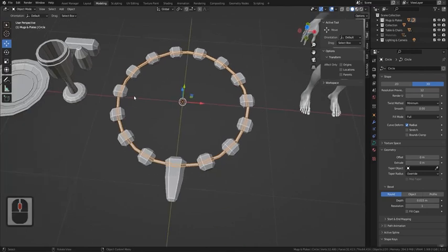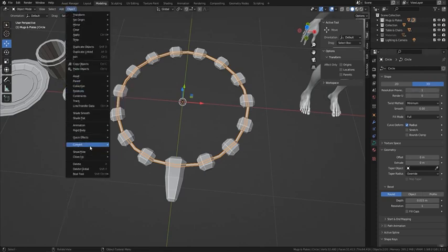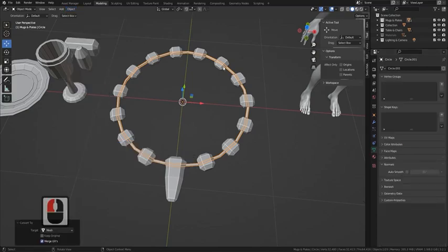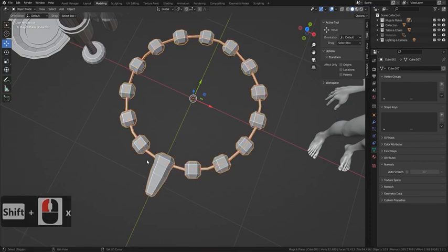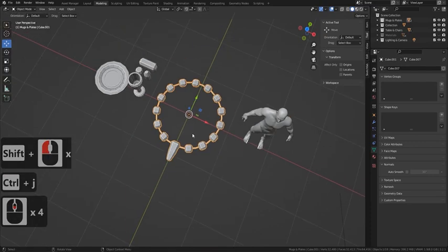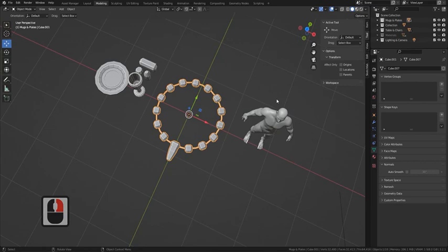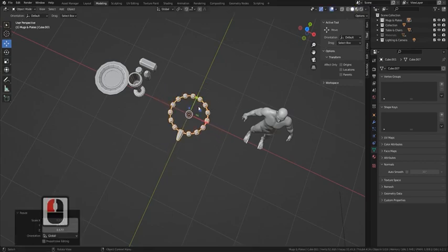Now, when you bring in a piece of mesh like this, normally I can't turn down the resolution because you've already created it. So this actually has no effect. Finally, all we need to do is come to Object, Convert, and convert it back to an actual mesh. And there we go. That's that finished. Now let's join all of this together. So I'm going to join all of this with Control J, press the G button, press the S button, like so, and there is our necklace.